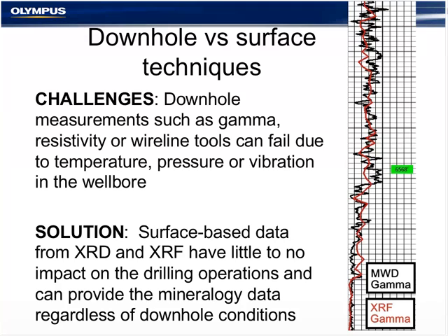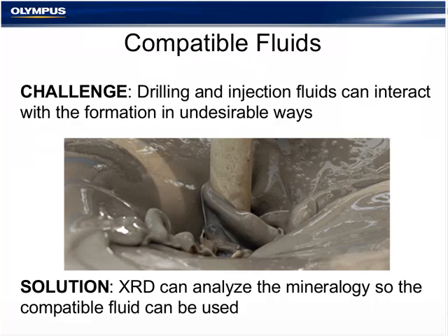X-ray diffraction provides easy identification of corrosion and scaling products with its on-site corrective actions. That's a great use to have this right on site. Certain clays and smectites will swell up in the presence of water. When they swell, they can trap the drill pipe and block up the well hole. Often in this case, you may want to switch to an oil-based drilling mud.